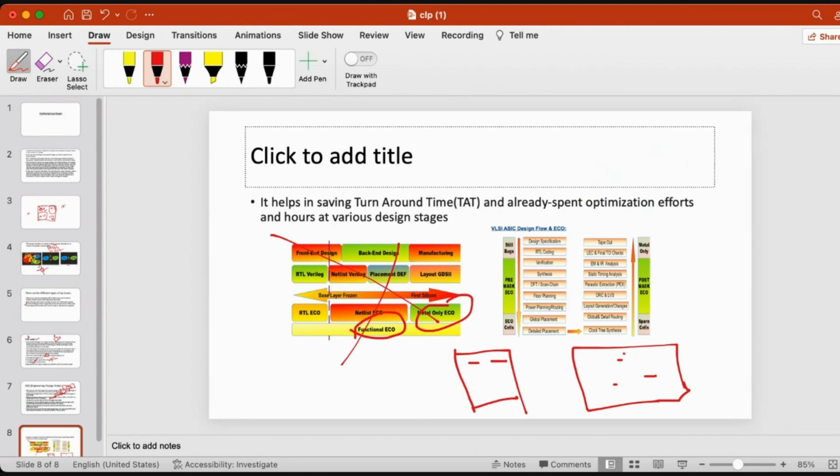So there are normal fillers, and there are programmable filler cells. During metal ECO, if you want to add some cell, then we convert this programmable filler cell into the required cell. If this programmable cell is a 2x cell, then we will convert this 2x drive cell into a buffer. In this way, we convert these programmable fillers into logical buffers. Then we will fix the timing.